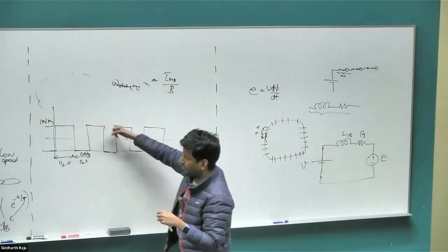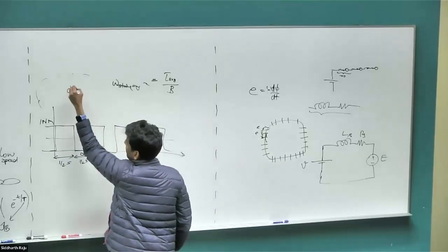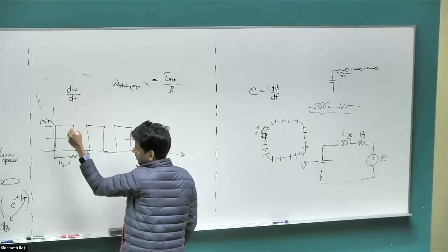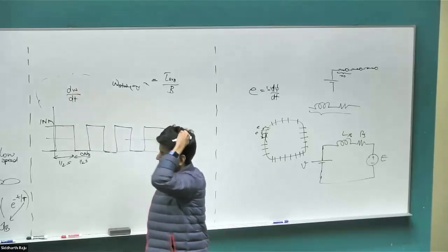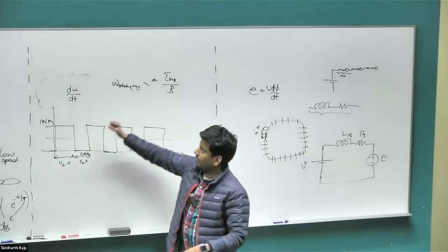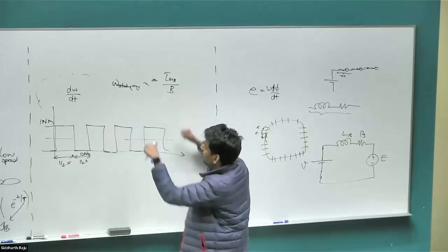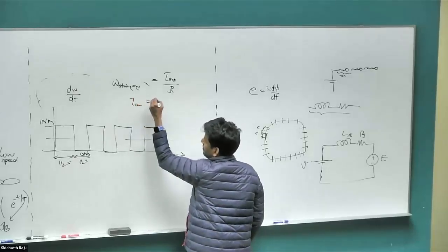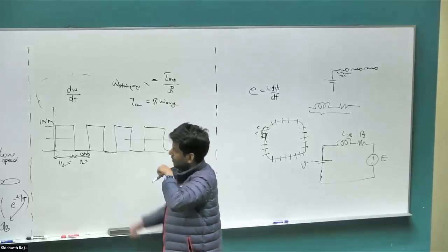On which you're having the harmonic component oscillate on top of it. The d omega by dt only acts on the harmonic components, because that's the only thing that's changing. If you have a constant value, the d omega by dt, again, same as the steady state logic, when we put it in average model, this term goes to 0. So the average value is just tau average is just b times omega average. That's about it.